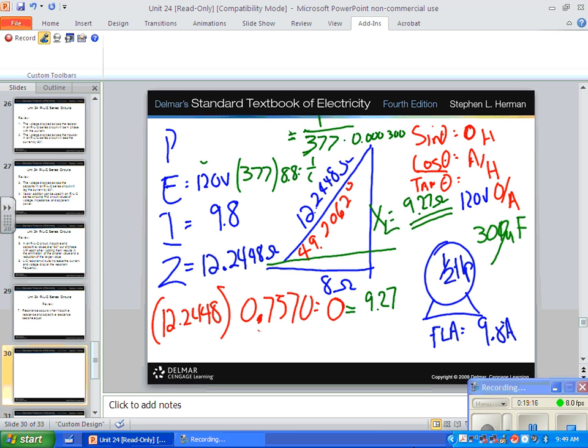Okay. So what you're saying is, let's ignore the 1 over first. Let's just deal with our point. Now I'm going to take this out and put in 0.0003, times 377. Probably going to get a pretty small number, like 0.1131. But what is that? That's the reciprocal of our X sub C, right? Let's take the reciprocal of this then, and we wind up with 8.84.